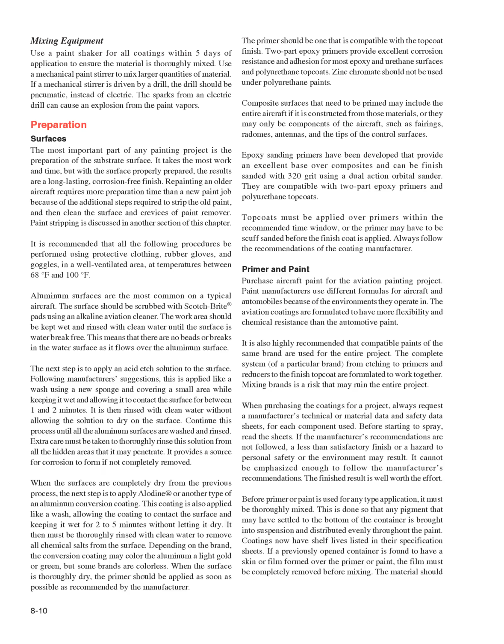Mixing equipment. Use a paint shaker for all coatings within 5 days of application to ensure the material is thoroughly mixed. Use a mechanical paint stirrer to mix larger quantities of material. If a mechanical stirrer is driven by a drill, the drill should be pneumatic, instead of electric. The sparks from an electric drill can cause an explosion from the paint vapors.